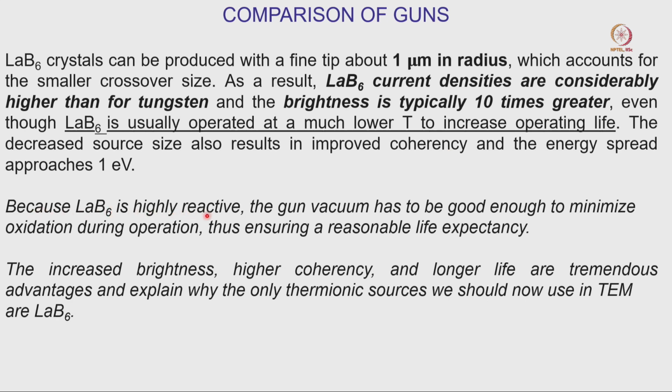So, LaB6 is highly reactive and the gun vacuum has to be good enough to minimize oxidation during the operation. That is one of the main points. As I told you, lanthanum hexaboride is a very good filament, and it is 5 to 6 times more expensive than a normal tungsten filament. Now, if your vacuum is not good, if there is a lot of oxygen or moisture, it is going to react with your lanthanum hexaboride and oxidize the crystal, and the crystal will break immediately.